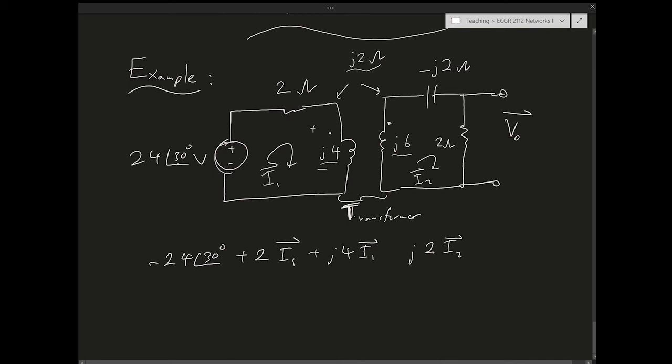And I want to determine the sign. I2 is exiting the dot, so this is going to be negative, and then the polarity of KVL I'm doing here matches the polarity of the dot on the primary side, so this will remain negative. This will be 0.